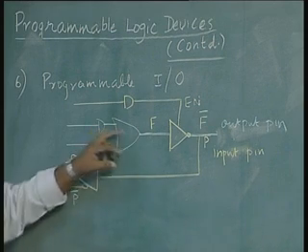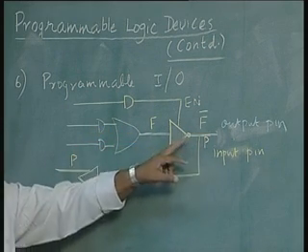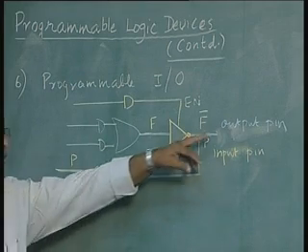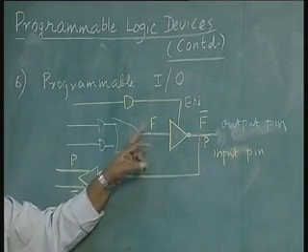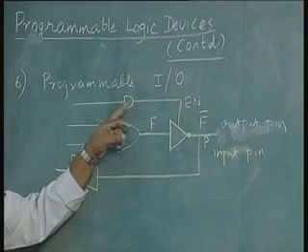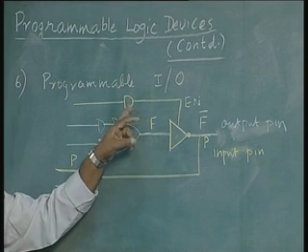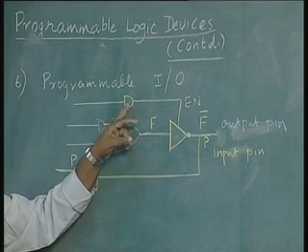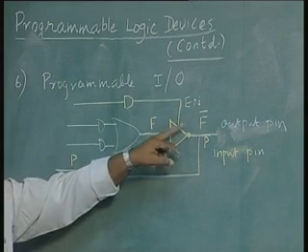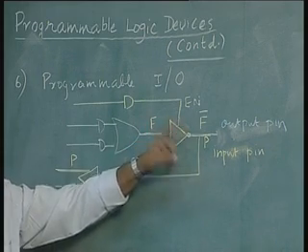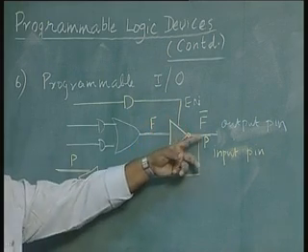So, this particular pin can be used as an output pin if there is a requirement for this type of combination logic output, by enabling this gate and thereby this buffer, by giving the proper input combination to the gate, so that this buffer is enabled, and output f or f bar, whatever it is, is available.